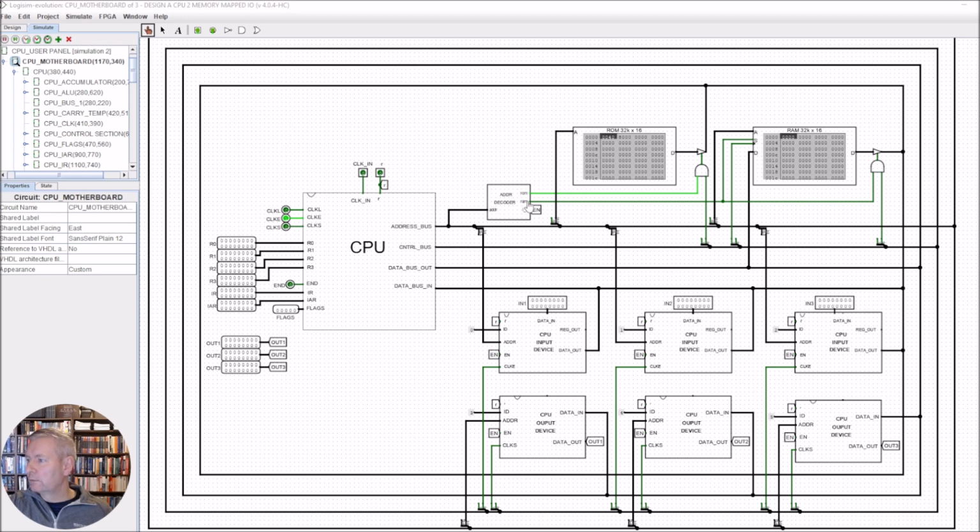So that address decoder will come in, and it's saying choose the RAM. Again, it's choosing the RAM, that case there, for the enable. We can choose the same point here for the set. Okay, so that's telling it, yeah, we're talking to the RAM, and then the enable, the set here, will tell us actually we know we're talking to the RAM, but this tells us we're going to write into the RAM.